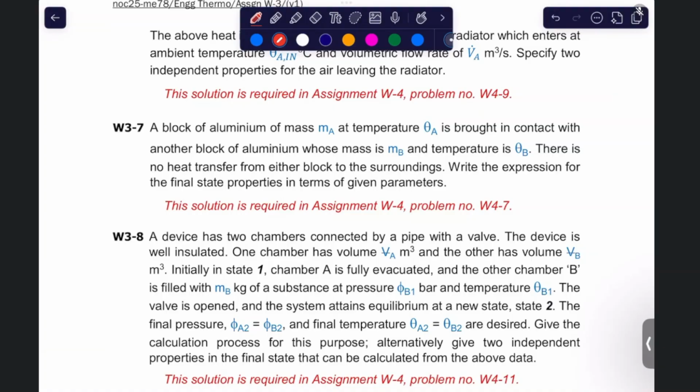Okay, so Qa, the heat lost by A, equals Ma Cp. Both are coming to a common temperature that I'll take as theta final, and the initial temperature of A is theta A. Here also Qb equals Mb Cp times the common temperature theta final minus theta B.